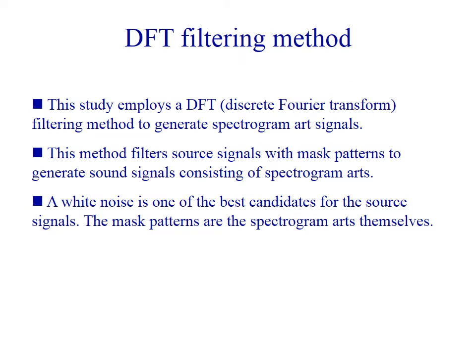This study employs a DFT filtering method to generate spectrogram art signals. This method filters source signals with mask patterns to generate sound signals consisting of spectrogram arts. A white noise is one of the best candidates for the source signals. The mask patterns are the spectrogram arts themselves.